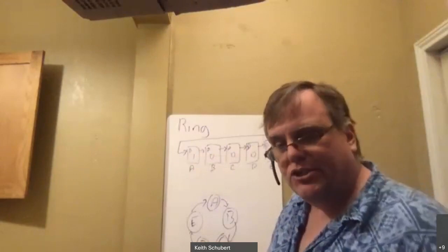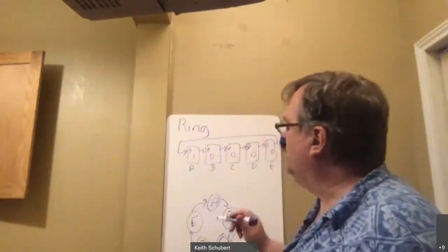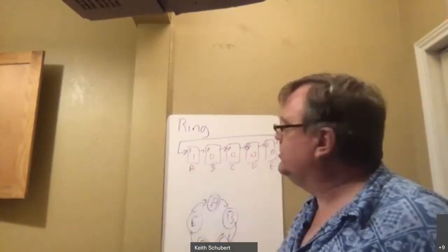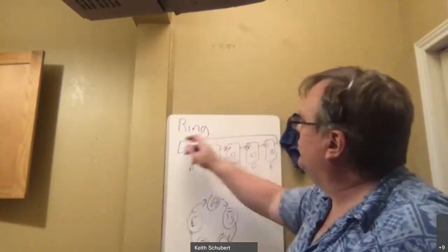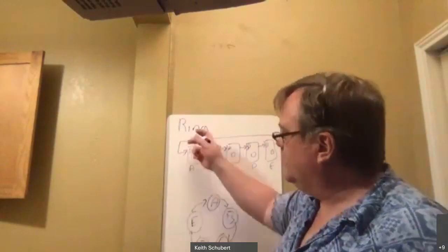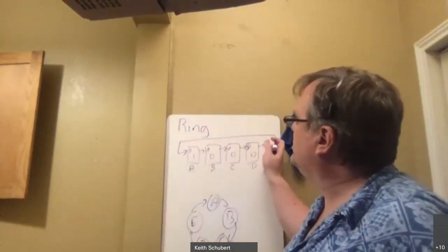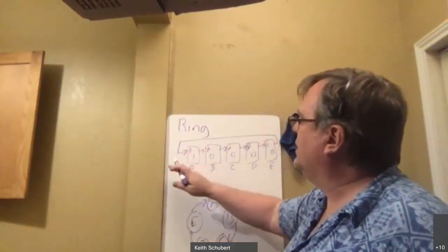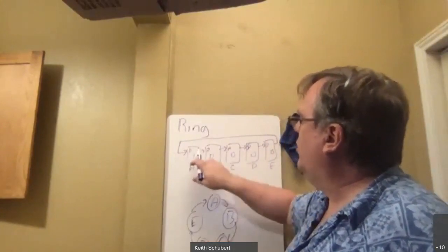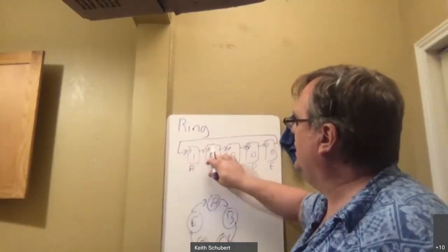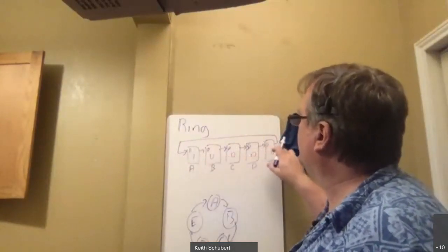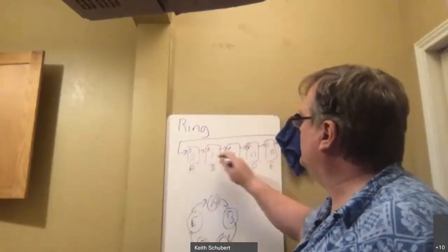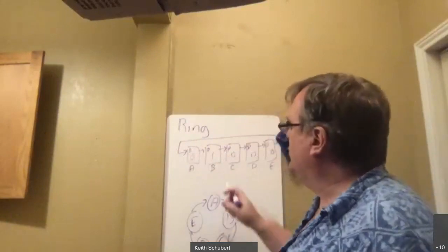We talked about how we can make a shift right and a shift left in a previous class, I think it was actually two ago, for these serial registers. But all I have to do for this clock is just hook it around. That's called a circulant setup, and that's where the name ring comes from, because it just hooks the output of a shift register back into its input. And so if I give it the command to shift right, this one will shift over to here, that zero comes around, the one shifts, and all the zeros shift down. And so it does exactly that count.